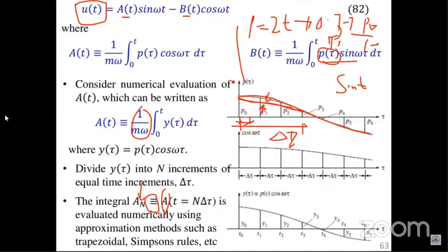If we are analyzing, because this dynamic analysis mostly will be for dynamic loads, for example, seismic analysis, wind loading, impact loading, that's why we start thinking of alternative materials or structural systems. You may think of using concrete filled steel tubes for our column, because we know steel is more ductile compared to concrete, and it is able to take more deformation than a rigid concrete structure. So that's why we are doing this kind of analysis.